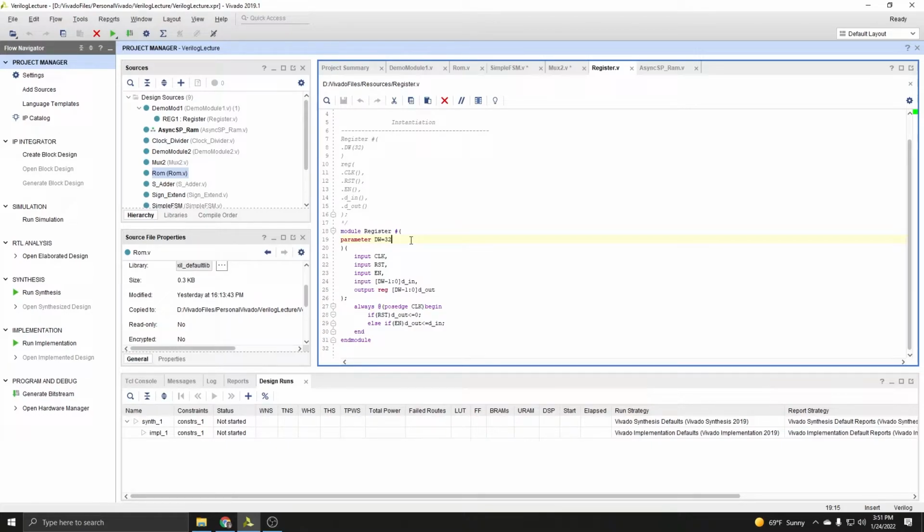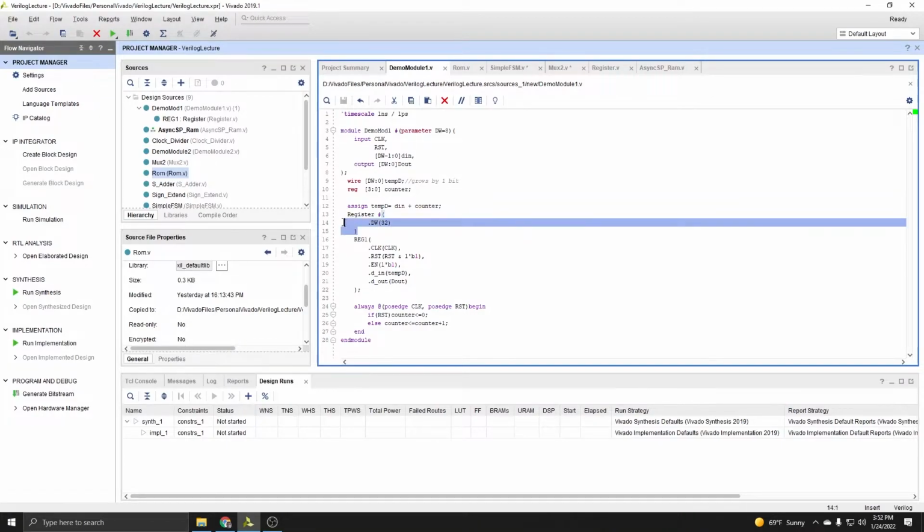The program counter doesn't have to be 32, you can make it whatever size you need, but not everything is 32 bits. Register addresses and stuff like that are 5 bits. But in many cases, the 32-bit will work. So you actually could very easily just not have this section here. This could very easily not be there.